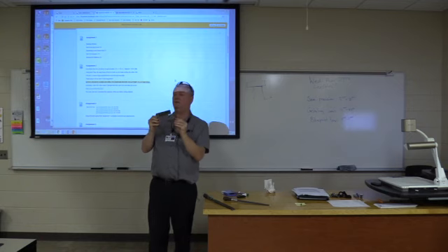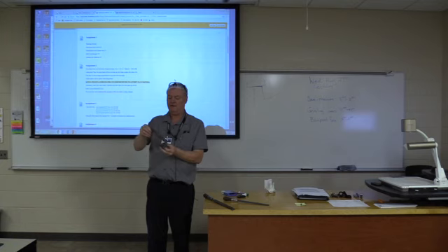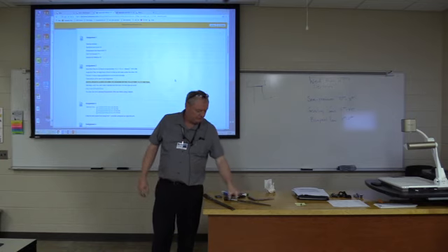Now you only need to do one saw cut edge, okay? You don't need to do both of them. Just clean up one edge so that it's perpendicular. This then will become what we call your reference edge. You will have the face, the side, and these three corners, and then you're going to put a little mark on there so that we know that that's the cleaned up face. All right? So we'll demonstrate all of that in a moment.